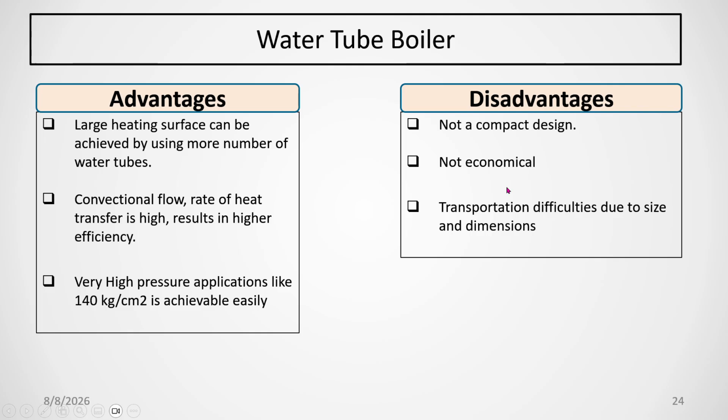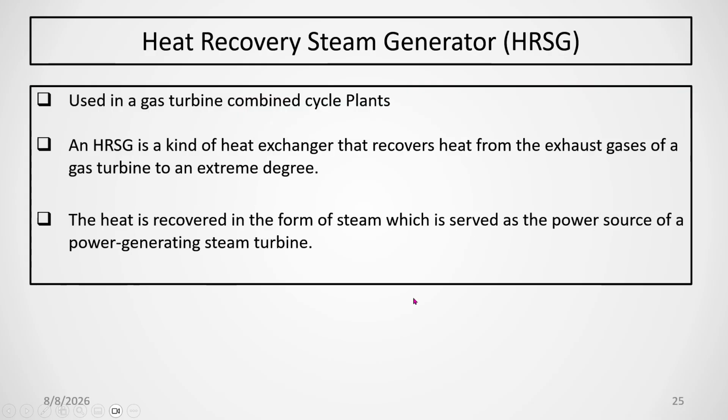The disadvantage is that it is not a compact design, the furnace surface area is high, it is not economical, and transportation will be difficult, because you have to erect all these things at site.